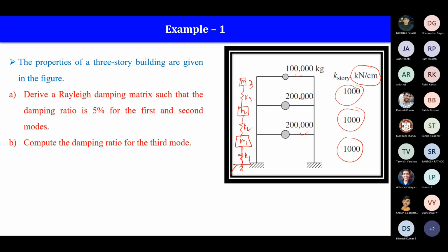So with this, we actually finish the formulation for the damping matrix. Basically, we discussed the formulation for the classical damping matrix, right? That is the mass proportional and the stiffness proportional, that is Rayleigh damping. So you have to remember what Rayleigh damping is. That is good enough for your level. Okay.